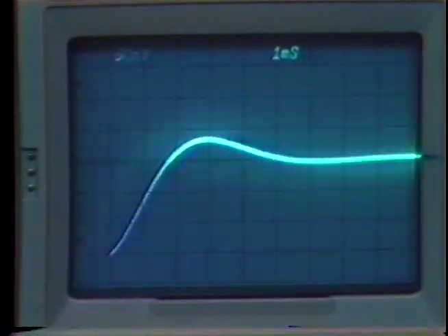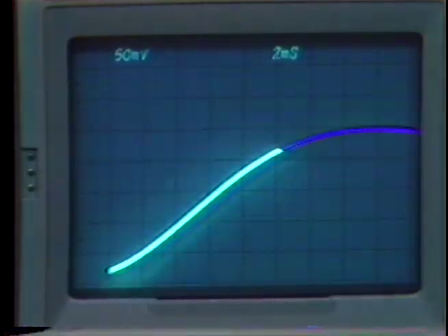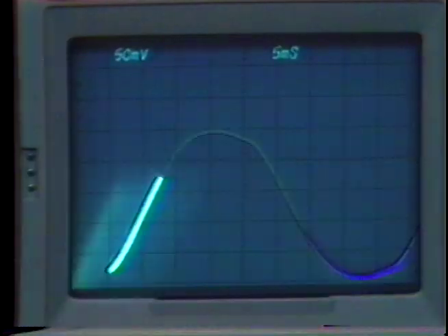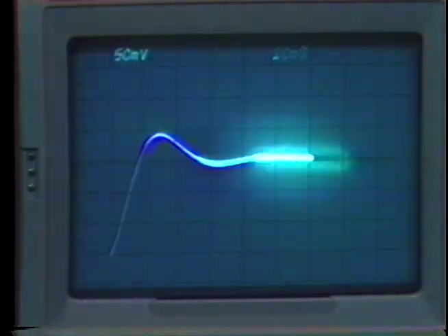Let's locate the pole at 10 hertz. We weren't even able to do that with 1 over S compensation. Things do get slower, but we have still a very well-behaved response, not excessive overshoot. And so we're able to stabilize the system.